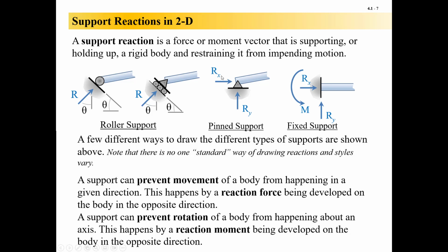Remember, the goal here is we've got to look at pictures and turn them into vectors, because statics is all about drawing your vectors and summing forces. So you have to be able to look at the picture and draw the vectors that are required. So here, just to go back, we found that you can get one reaction vector when you see a roller. You automatically know one reaction vector. A lot of times the roller is on a horizontal surface, like flat Earth, then the reaction's pointing straight up. Over here at the pin support, we have two reaction vectors.